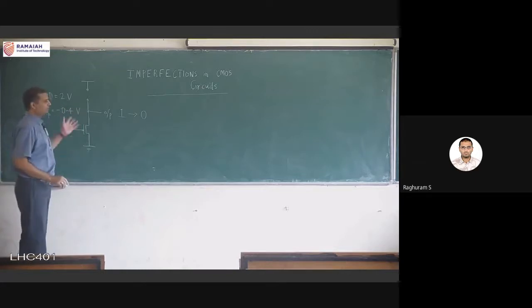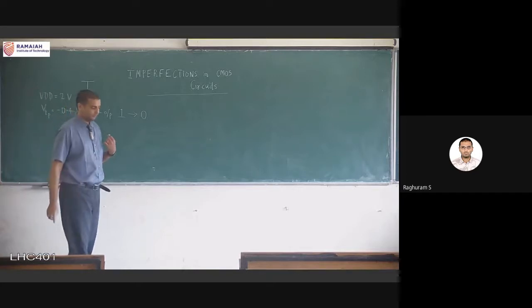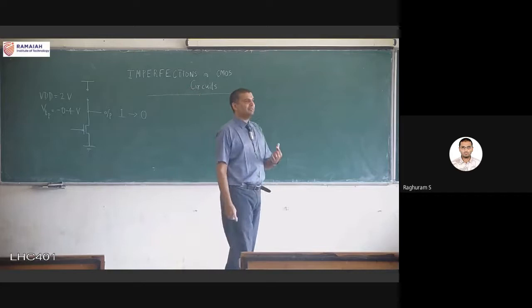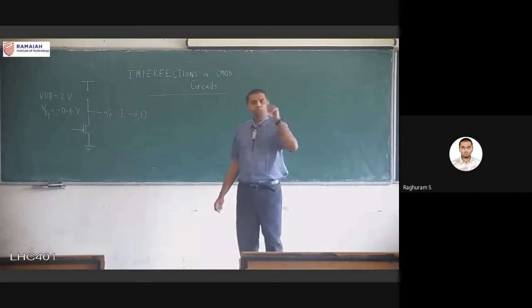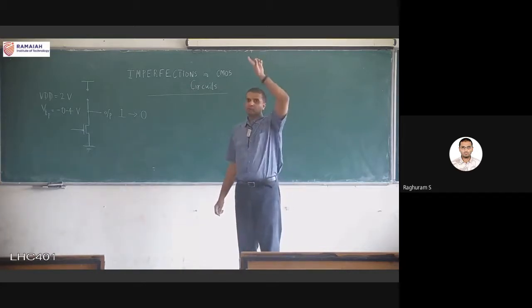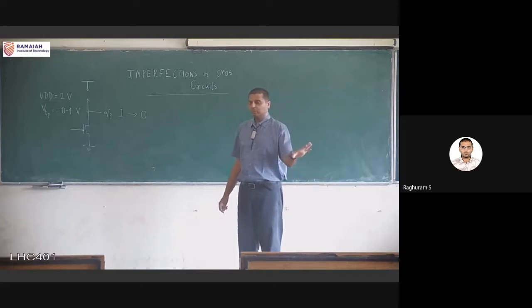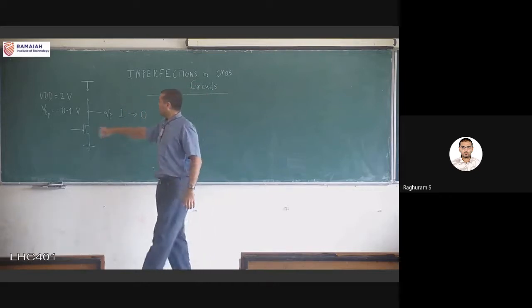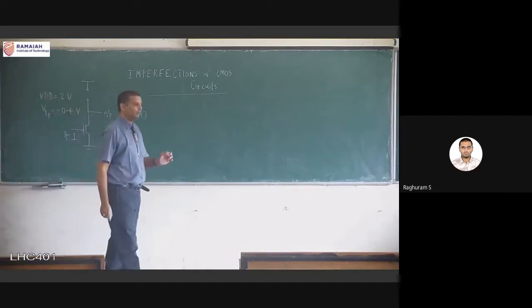Okay, so this is my situation. I have put the PMOS transistor in the bottom, and since we discussed that I will design circuits such that the output will be connected only to VDD or to ground, but not to both. Here, the top part, I don't even know what is there, but according to my design, it's going to be open circuit, because in the bottom part, I am having input equal to 1 for my gate.